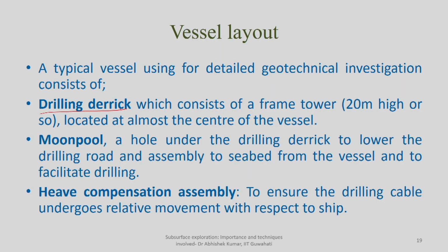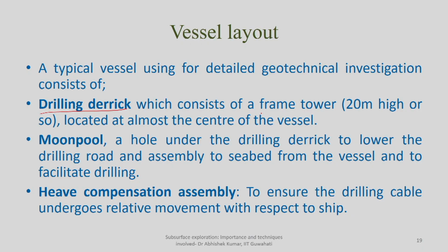The typical layout consists of a drilling derrick. A drilling derrick is basically a steel tower used so that you can lower the drilling assembly, because your depth of exploration will be very high. You can erect a significantly long drill rod through the derrick, and as the drilling progresses it will keep on lowering. It consists of a frame tower 20 meters in height, located almost at the center of the vessel.